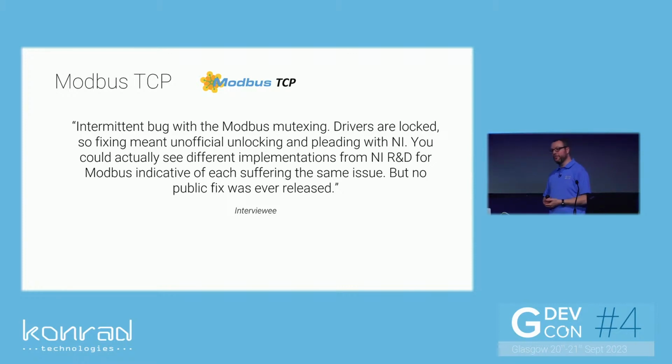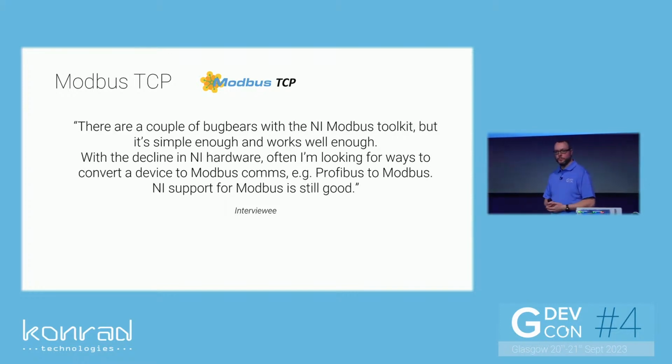So that suggests that the standard NI Modbus drivers might have a problem, so you might be better off looking for a different one. Someone else: there are a couple of bugbears with the NI Modbus toolkit, but it's simple enough and works well enough. With the decline in NI hardware, often I'm looking for ways to convert a device to Modbus. So that's a good idea. If you've got a Profibus slave, switch it to a Modbus device, and then there's a really good chance you'll be able to talk to it much more successfully.